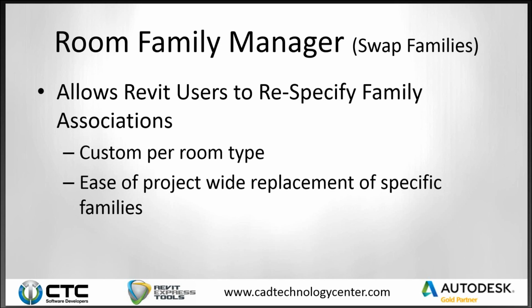So what you can do is room by room, tell it which actual families you want to use. In this case, we'll be taking a look at a middle school / high school project, and possibly the student desks used for younger students might be different than student desks used for some of the older students. And so that's why this has the ability on a room type by room type basis to swap it out. The designer might just say, I need 30 student desks in this space. But as time goes on, you want to refine that. The actual space those desks take up might be a little bit different depending on the age group. So this gives you a really easy project-wide replacement for those specific families. It makes that management really easy.